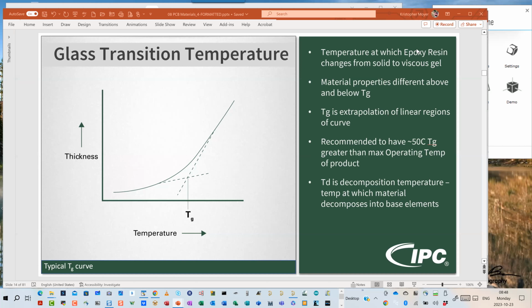Yeah. So where you're going up to those elevated temperatures, that's where you're looking for those problems. Now, will they cause problems? Potentially. Will they cause reflection problems? Probably not if you've designed your board well, unless you're in the RF world, where your fundamental clock frequencies are in the multiple gigahertz or double-digit gigahertz or higher frequencies. In those cases, yeah, the expansion from the board itself might be a problem.